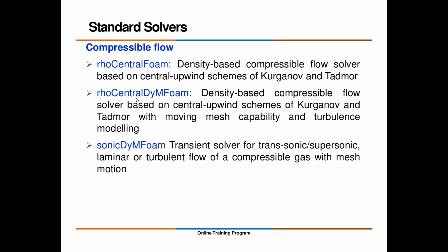This is the center form, DyM form. Where there is a DyM, that means it has the capability of mesh movement. That is how you can see this is sonic with the mesh movement capability. Wherever you see dynamic mesh, DyM, that means dynamic mesh movement. Wherever you find any of the forms with a DyM, it comes with the mesh movement capability.